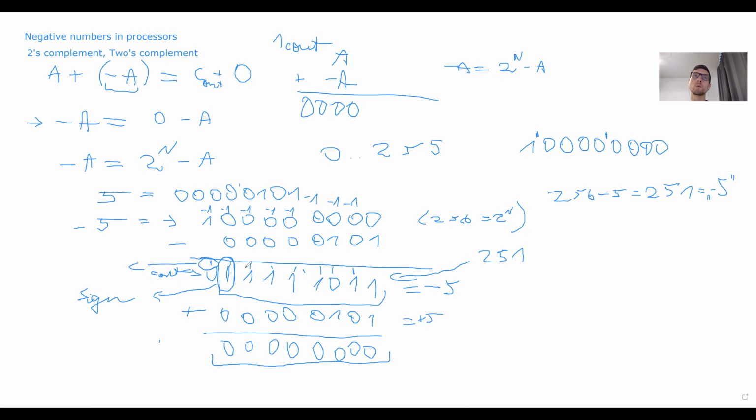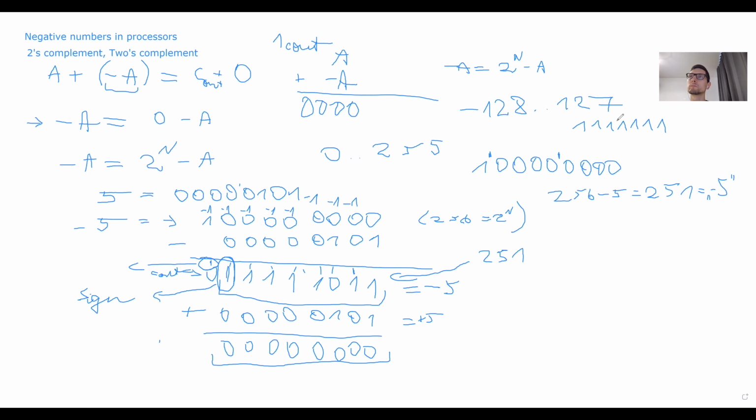Of course, if we are using 1 bit for sign, then when we use numbers in 2's complement, we get combinations only from minus 128 to 127. So how do we get this 127? Very simple. We write the largest positive number that we can imagine, but only in 7 bits, because the 8th bit in front is 0, so that it's a positive number. So this is 127 with 0 in front, so it's plus 127.